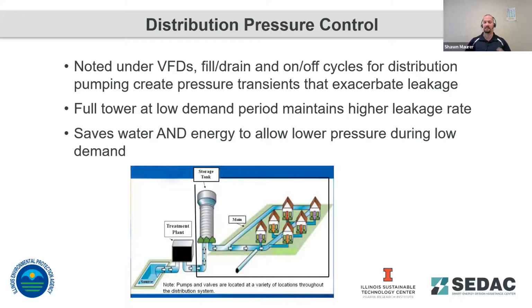Something else to look at is, again, if you've got storage capacity in multiple storage towers and maybe some ground storage tanks, you can look at during low demand periods in the middle of the day or late at night, does the tower have to be full then and maintain peak pressure in your system? Or can you let it coast down a little bit for a few hours in the middle of the day, a few hours overnight, reduce your amount of leakage that you have in your system during those particular times of day, and then fill the tower back up during your peak demand periods or just before those periods by ramping up your pump slowly to refill that tower and meet those peak demands.